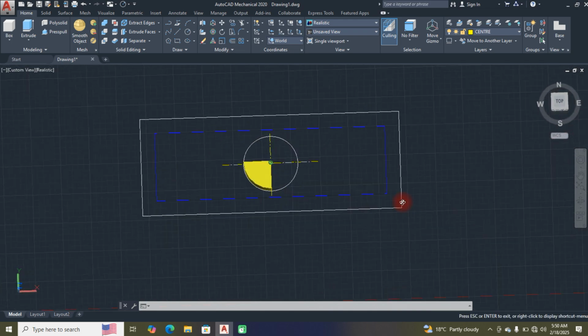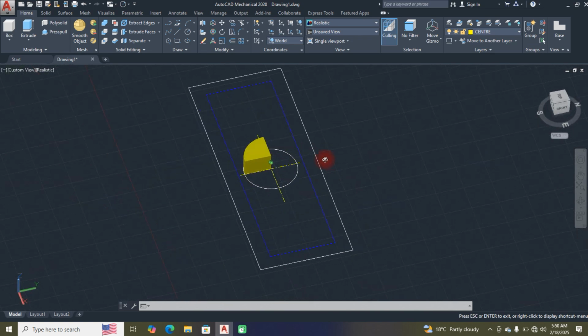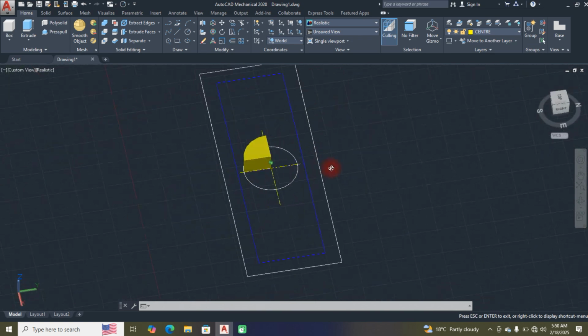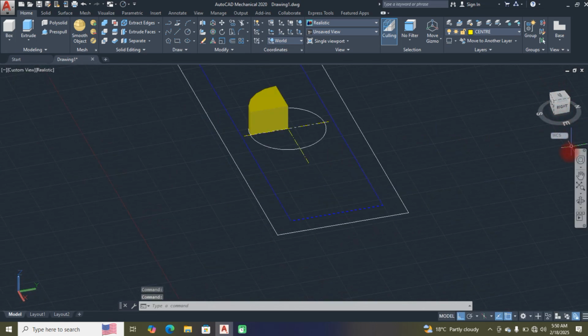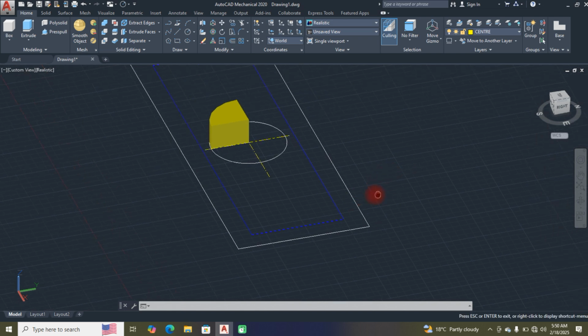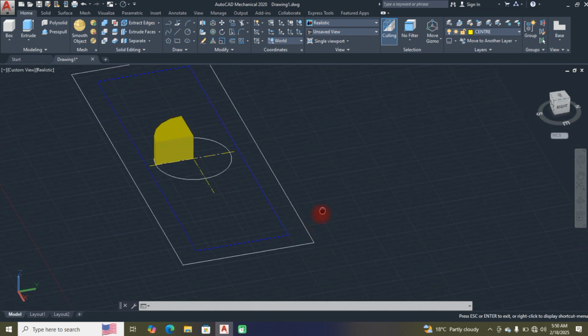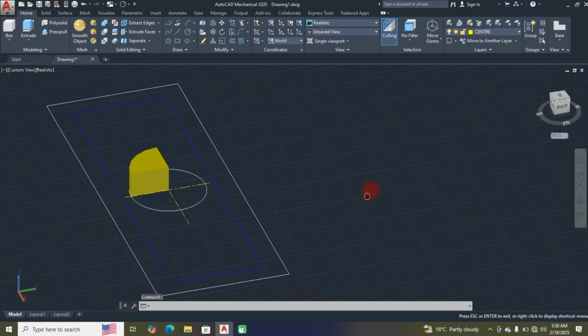But for this, you can see if you just hold shift, you'll have a 3D view of your object. Okay, so these are the commands, you can just access them here. For example, this is the orbit command that I'm using, shift and holding down the wheel on my mouse. To utilize the pan command, I think for now we are conversant with it. You just hold the wheel on your mouse and you drag to pan your object like that.